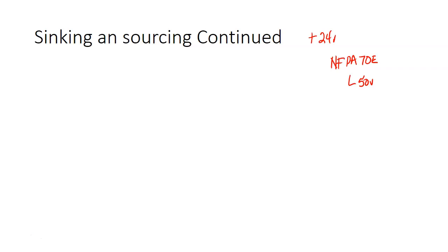So the predominant voltage on current PLCs is 24 volts DC. It doesn't mean you can't run AC devices. It means 24 volts DC would be the output of our outputs, and then we could run that into a relay. Does everybody understand relays? Anybody got any problem with relays? Okay, we've got something here that shows that in a minute, so we should be okay.